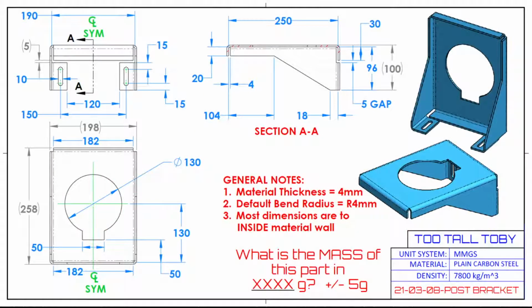So this next challenge is a sheet metal challenge that I threw out there for everybody on Saturday. It's kind of a tricky sheet metal part. This is one of these spots where the customer gave us material inside instead of material outside. This happens most often with electronic enclosures. So you know what the dimensions of the PC board are. You kind of know what the interior height is of the heat sink, or whatever it is that's going on inside of that electronics enclosure. And so those are the dimensions given to the sheet metal team. And then a lot of times they just end up dimensioning it all to the inside and kind of building the material outside. So that's what's happening with this print too.